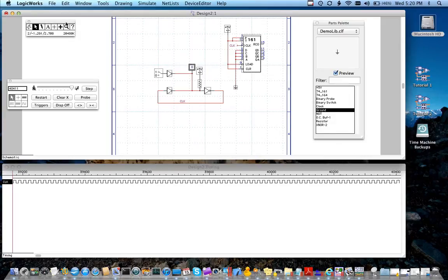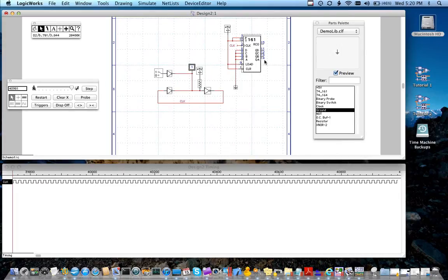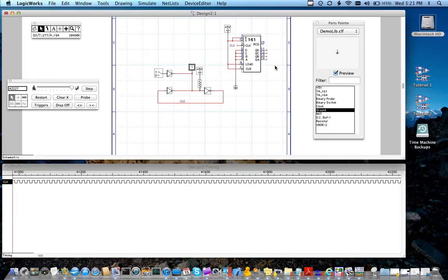Okay, I want to demonstrate another little option when you're naming signal lines. So let's start by pulling a few signal lines off here. I just do this because otherwise we might accidentally select pin numbers as opposed to signal names when using the naming tool. So it's a little easier if there are these little stubs there.